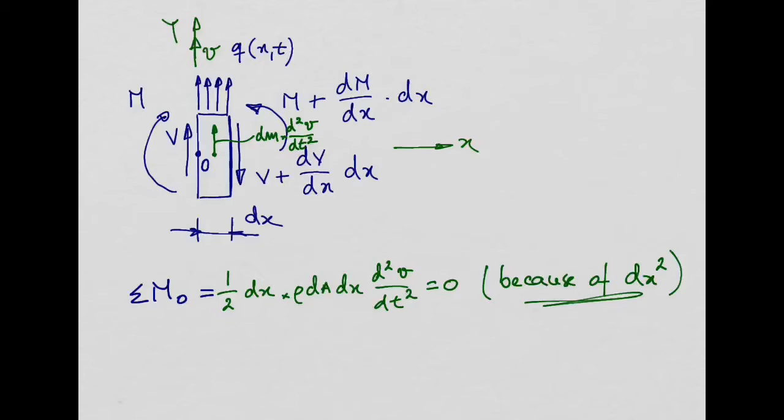So it's there so you don't forget why. So this is again still Newton's second law, now for the moments: the summation of moments equals the moments produced by the inertia forces, right? We are, of course, in this case, neglecting the rotational or angular acceleration of the beam. So we are only considering the linear acceleration along the deflection direction of the beam.